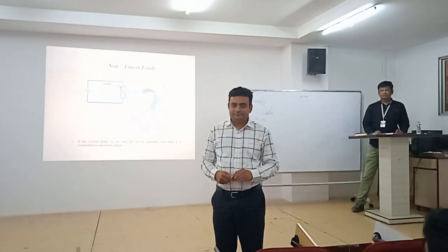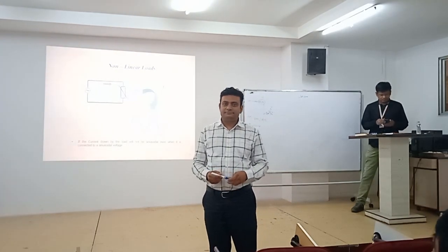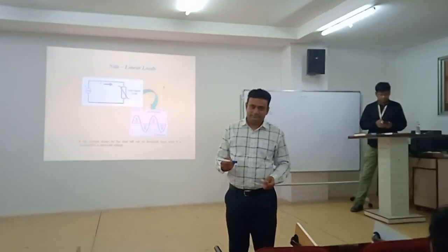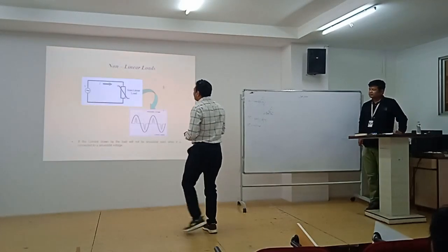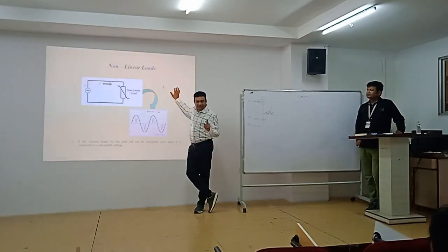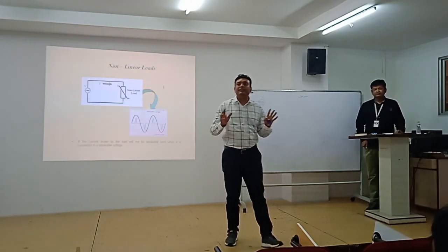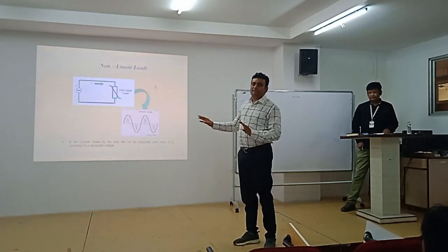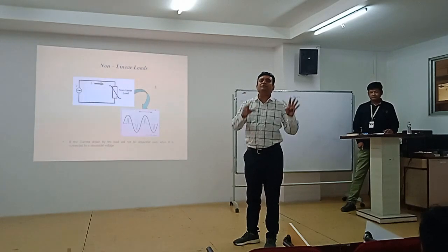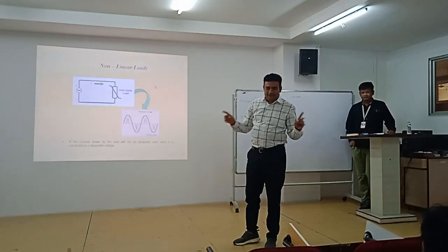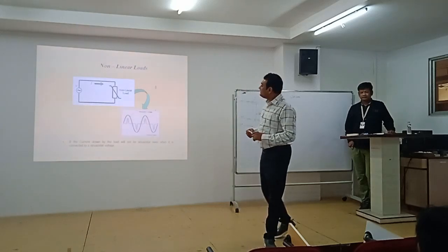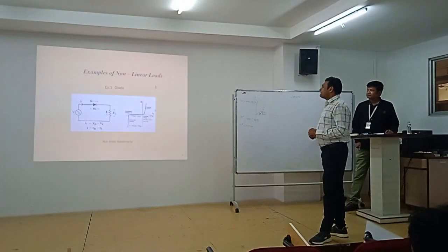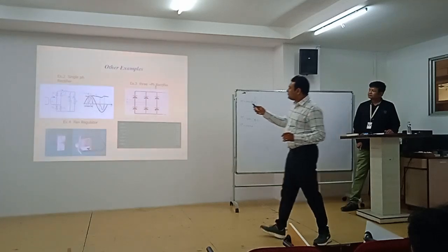Non-linear load: a rectifier, after converting to DC at the output side, and the current that is drawn by the input side of the rectifier will not follow the pattern of the voltage. So it is a non-linear load. Non-linearity exists right from the diode. If you take power electronics, semiconductor devices start with non-linearity. So any kind of power electronic circuit, whether converter, drive, or arc furnace, everything is non-linear because the current doesn't have a linear relation with the voltage. So it is called a non-linear load. Next. So these all are non-linear loads.